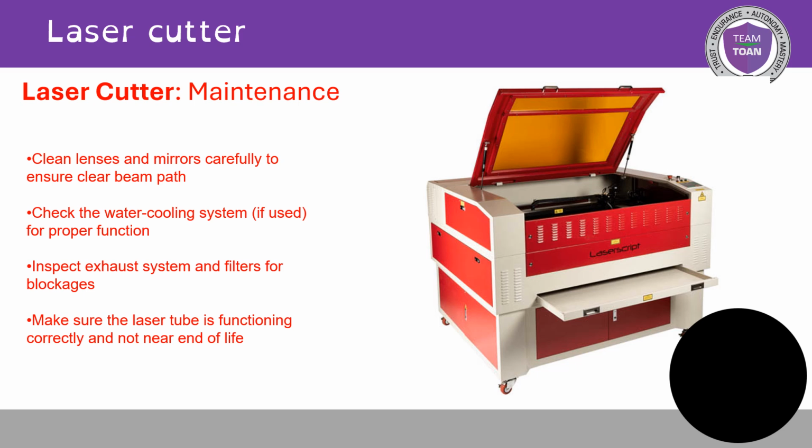Laser cutter. So laser cutters work with lenses and mirrors, so you need to make sure that they are clean to get a clear beam path.